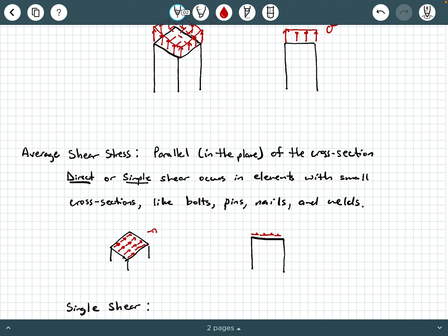We usually call shear stress tau, the Greek letter tau. Now, tau is going to be equal to a shear force divided by a cross-section area of some sort. So we abbreviate this as tau is V over A, because V is typically the letter we use for shear force. Remember, shearing creates a slicing effect. Axial or normal forces tend to stretch or compress things, but shear forces tend to create a slicing through something, and that slicing effect will be parallel to the cross section.